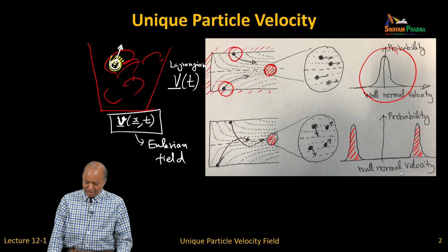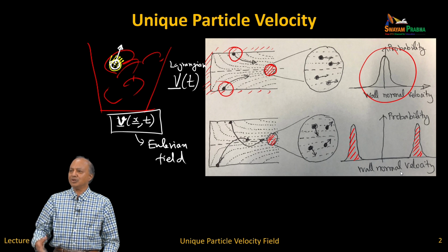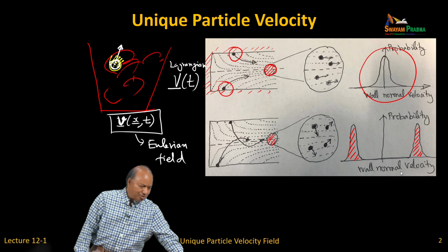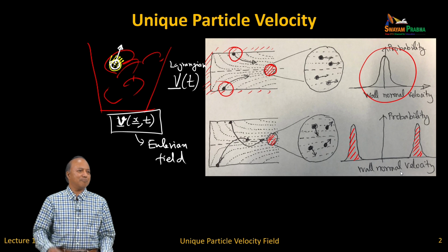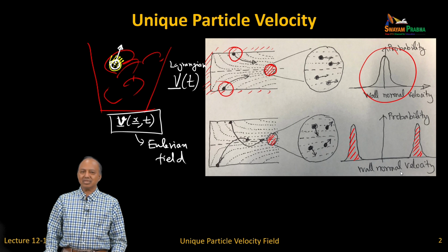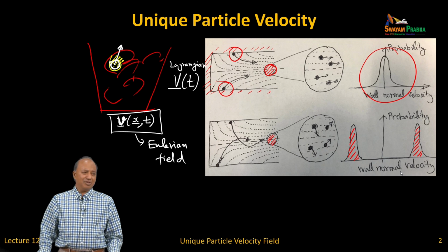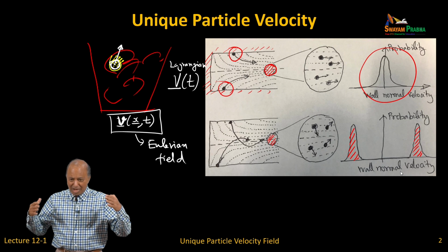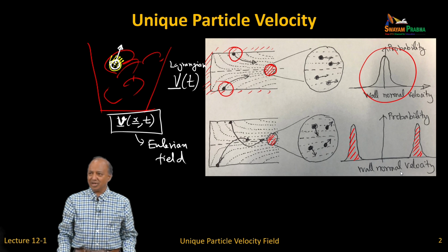then Euler-Lagrange method may be better, because towards the end in this chapter I am moving towards trying to tell you, if you have a problem, one of the big questions is, should I use Euler-Lagrange, should I use Euler-Euler, what kind of method is good for me. So I was trying to come up with some simple recommendations. In that sense, you calculate the Stokes number. If the Stokes number is order 1, Euler-Euler is good. If it is really large, then Euler-Lagrange may be a better thing, because you are tracking the same cell can have different particles going in whatever way they want. You have no restrictions. You are not talking about the average.